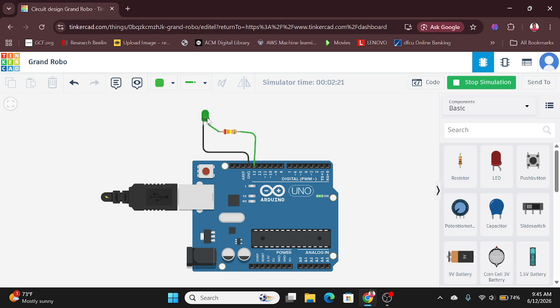So if your LED does not blink correctly, check your wiring first. Secondly, check the resistor placement. Third, you can check the pin connections. And if all that is well, then you can debug the code. Do the debugging, look for errors, you troubleshoot. These are also important skills in embedded systems learning and real-life practice, because you need to have the knowledge and the skills to find out where the error is.